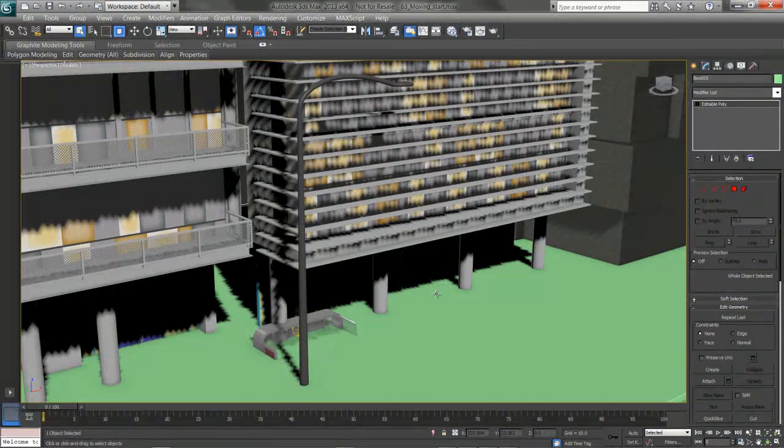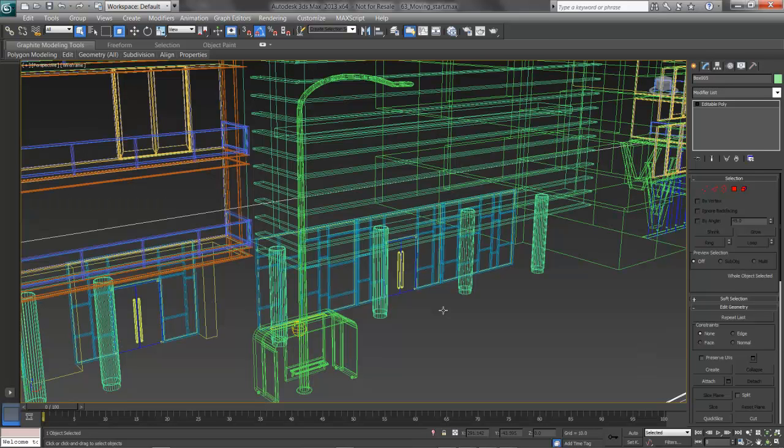In this video, I'll look at moving, rotating, snapping, and scaling objects in 3ds Max. We need to bring the tram stop all the way up through the sidewalk and pull the streetlight up as well. We also need to pull the sidewalk down to sit cleanly under the buildings, as right now, you can see when I change to a wireframe, it's clipping through the bottom of the columns.